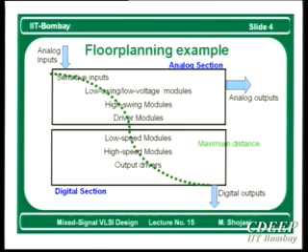For example, you can call it a mixed signal SoC. So the question is how I should place it. First of all, we start from analog inputs. Where do they come from? Analog inputs usually come from a sensor, which is the interface with nature. If they come from a sensor or from any natural resource in nature, usually they have three specific characteristics. First, they are not very high in level, which means the level of the signal is low. This is valid in many cases.